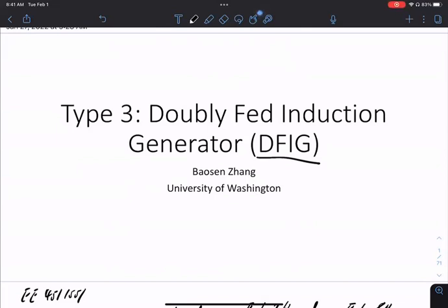So an induction generator does not do well with a standalone excitation because of frequency problems. You still need to be fairly synchronous. Yeah. Okay. So it's not a DC excitation. The excitation comes from the grid. So that's a good question. That's a difference between an induction generator and a synchronous generator. But still here, the main keyword is this doubly fed. And you'll see this a lot. Like this DFIG, still most wind turbines are this type. They're a fairly robust design.